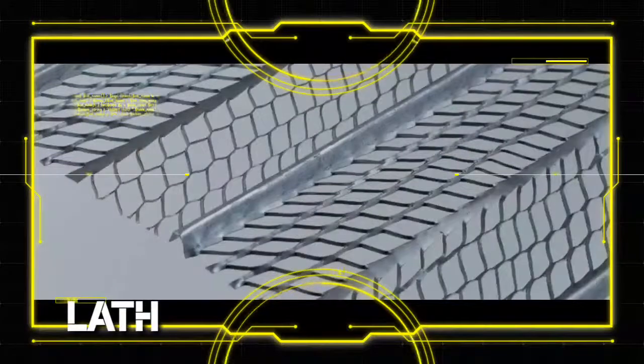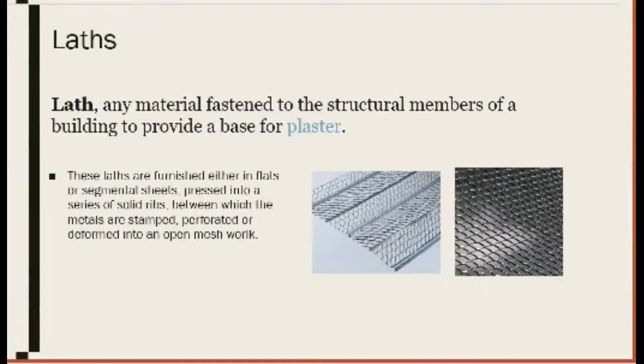And the last method for concrete reinforcement is the lath. A lath is any material fastened to the structural member of a building to provide a base for plaster. Plaster is used for coating walls, ceilings, and other partitions. These laths are furnished either in flats or segmental sheets, pressed into a series of solid ribs between which the metals are stamped, perforated, or deformed into an open meshwork.